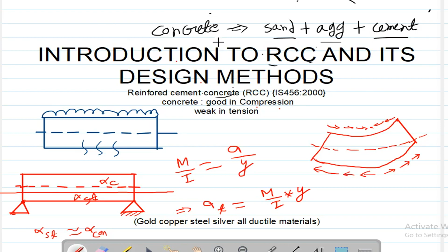So in some places we find more sand, in some places more aggregate. Many boulders sometimes get isolated in one place when we mix the concrete, and in other places only cement particles are found in larger amounts. In smooth plastering, sometimes cement and aggregate mix up more. So we can say concrete is a heterogeneous mix.